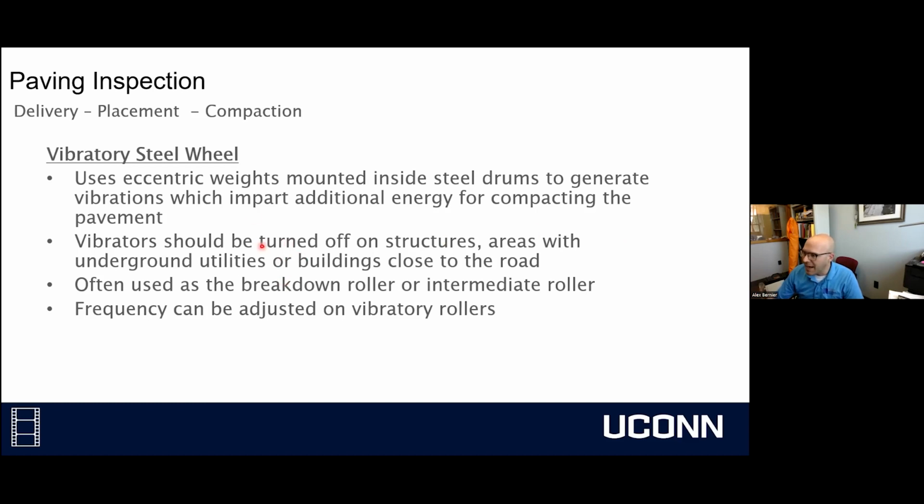And then we most likely are going to be using these rollers in the breakdown position when they're vibrating. And we don't use vibration in the finish position because they're actually making marks in the pavement. So it would not be a good finished product. Sorry, what I'm trying to say is, as the rollers are changing direction, they also are going to be turning their vibes on and off. And the reason being is if they come to a stop with their vibration on, they're going to mush the pavement and cause it to slide. So you'll notice that they stop as they change direction.